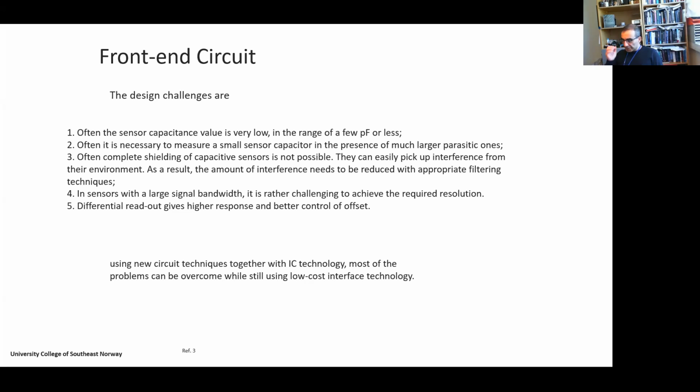And when you have these capacitors, the signal is so low that it can basically drown in other types of signals and noise. So sometimes we need to shield the sensors.